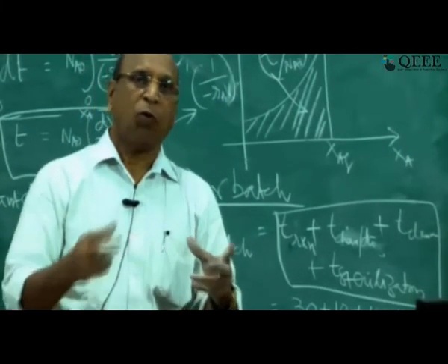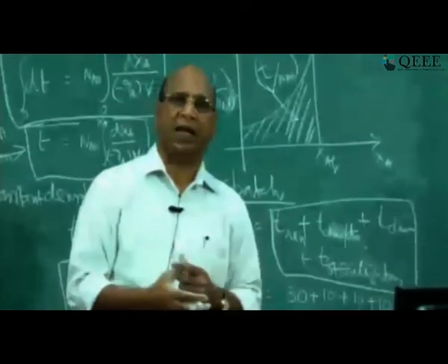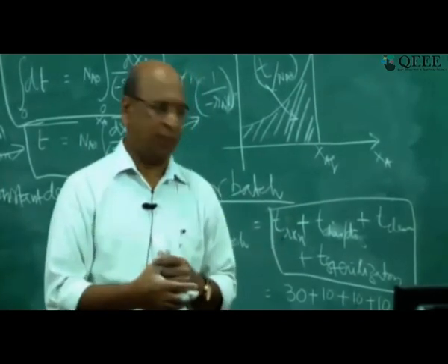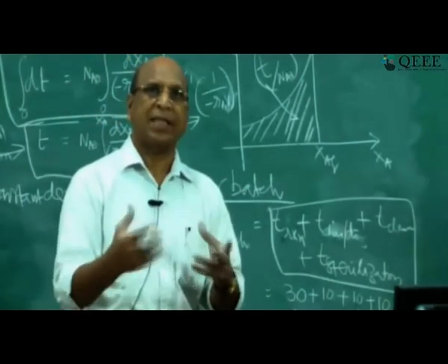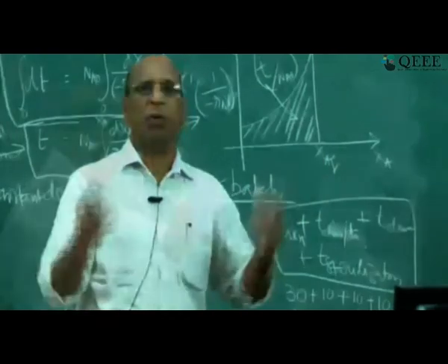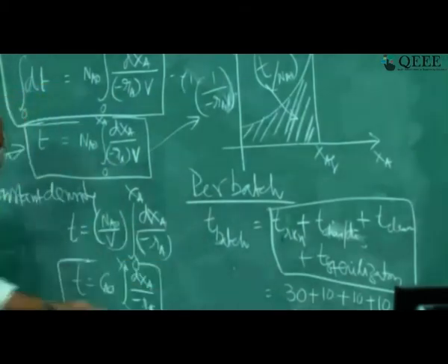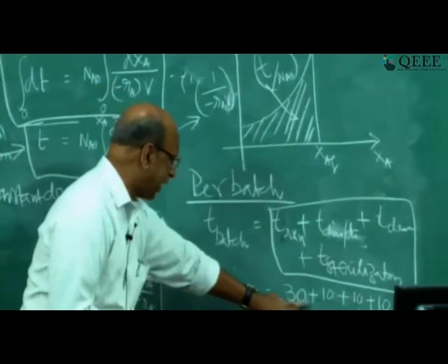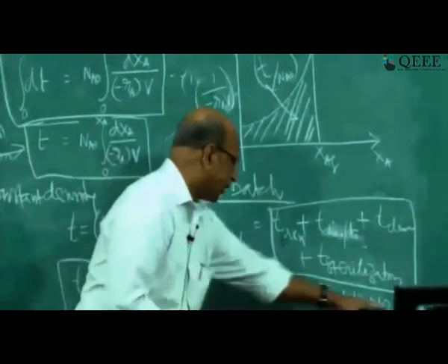material. Now if you know the density of this 1 ton reaction mixture, let us say 1000 kgs per meter cube, that is the density of water, what I am telling, right? So if you know that, you can calculate the volume of the reactor. Now you see, once you calculate from this integration what is the time required, that time I am saying it is 30 minutes. For all other things you have another 30 minutes, so